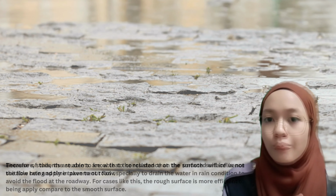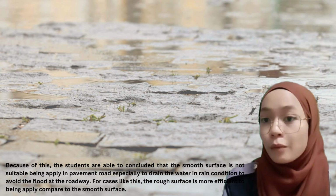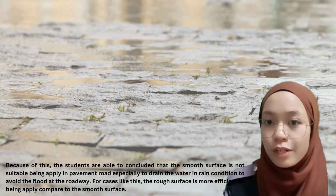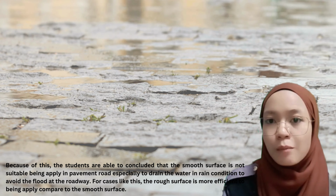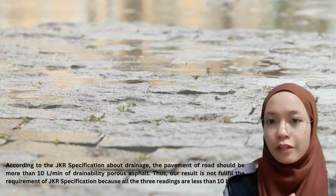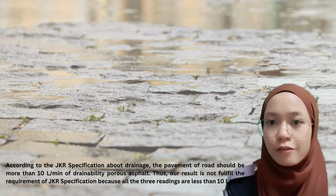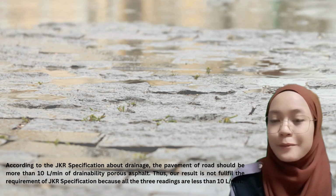Therefore, students are able to conclude that the resistance of the surface will influence the flow rate and the time taken to outflow. Because of this, the smooth surface is not suitable to be applied in road pavement, especially to drain water in rain conditions to avoid flooding at the roadway. For cases like this, the rough surface is more efficient than the smooth surface. The JKR specification for drainage of porous asphalt pavement should be more than 10 liters per minute. Thus, our result does not fulfill the JKR requirement because all 3 areas are less than 10 liters per minute.